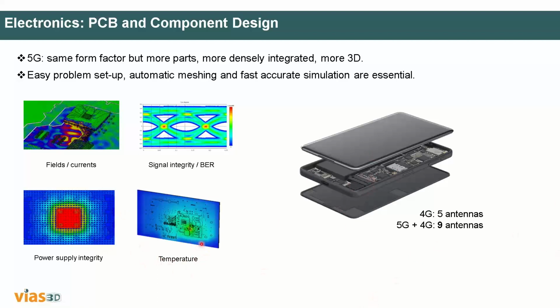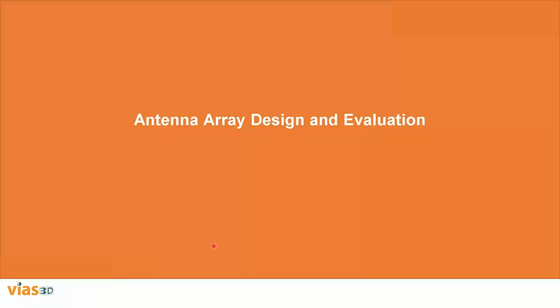Then you want to see how much temperature rise is there, because as the temperature increases, most of the ICs, transistors, whatever is in the PCB, may get damaged. So you want to address that as well. Then the second thing is antenna to antenna coupling, antenna to PCB coupling. There are so many things. Actually, I removed all the slides to save time.